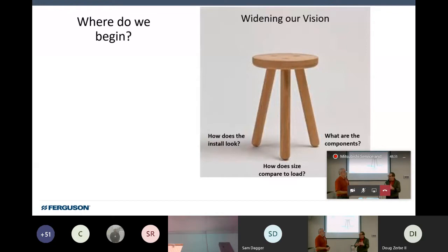You have now burned up 30 minutes of your time in the home, in the bedroom, setting up, looking at the unit. And then what we get all the time is a phone call, and we'll say, okay, so what are you working on? Oh, a GL unit in '09 hanging on this wall. Well, what is the complaint of the consumer? Well, it's this. Can you tell me what you have outside? No, I haven't been there yet. I don't know. Or is there a branch box? I think so. I'm not sure. Okay, does every line set run to the unit?